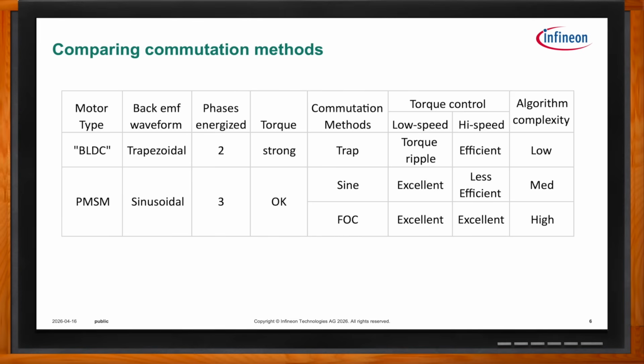You do trade off a little bit of torque for this sinusoidal commutation. However, what you gain is really excellent torque ripple and control. You can have extremely smooth torque. This is why it's so good for servo motors, is that you don't have that herky-jerky kind of commutation going on. It's just super smooth commutation at any angle, at any speed.